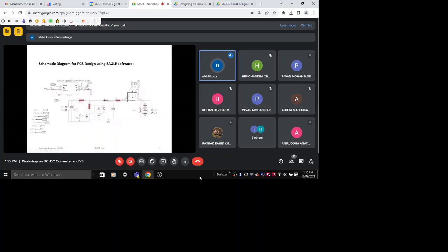Then there is a resistance between the gate driver and the gate. Without it, the gate circuit will get overheated. There could be extra power loss at the gate driver. So typically, by thumb rule, you can take 10 ohms up to 22 ohms for this gate resistance.